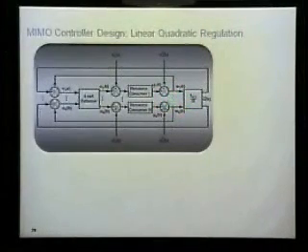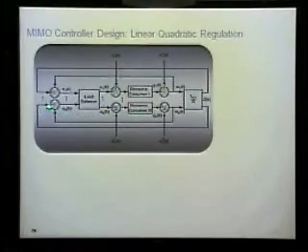So the way we did that balancing of the response times is that the reference input for each one of these controllers, for each one of the resources over here, the reference input that we used was actually the mean value of all these response times. And so if we could drive each one of the memory pools to the mean value, then we've got it balanced. And that's the technique. That's what this diagram says here.